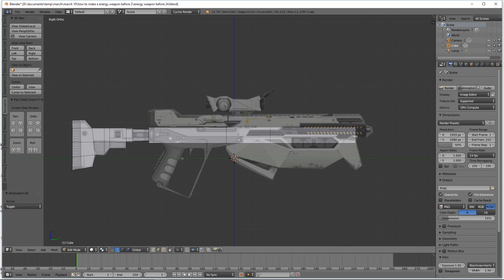I'm going to still hover here, hold Control, and while holding Control, press R. I'm going to left click one time. Because I left click one time, I can move this loop cut. So I'm going to move it right here and then left click a second time to lock that loop cut in. I'm then going to press A to deselect.